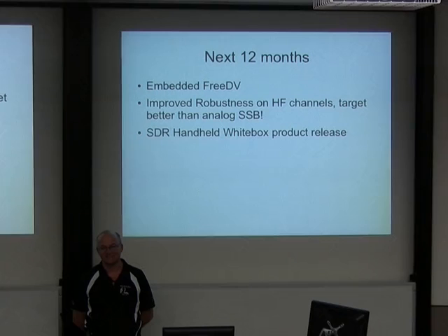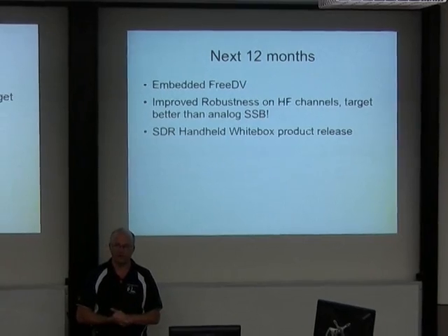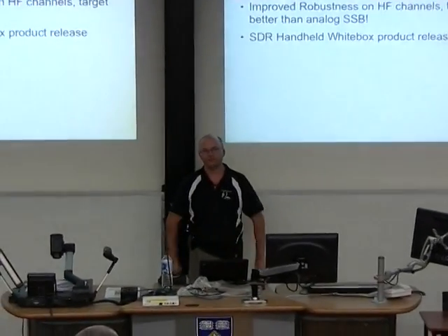Is there any work being done on higher bit rate open codecs? No, not that I know of, over radio, but there are a subset of people who are interested in, say, wideband SSB and AM radio, and some people have suggested there is a market for that. The actual analog bandwidth is only about 1.2 kilohertz of this signal. It's much narrower than SSB. So there's room in, say, a given narrow band SSB bandwidth to have higher quality audio if you've got the signal to noise ratio to support the bit rate required. You don't want it breaking up in bit errors if you're trying to get higher quality.